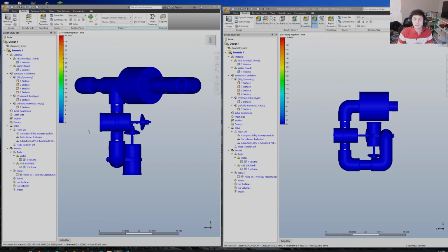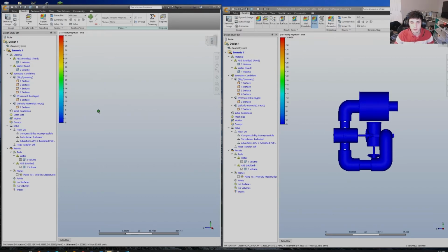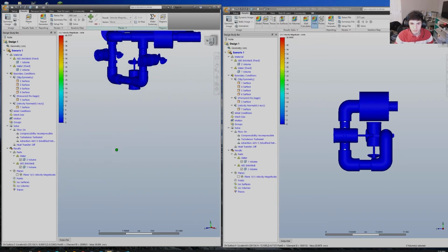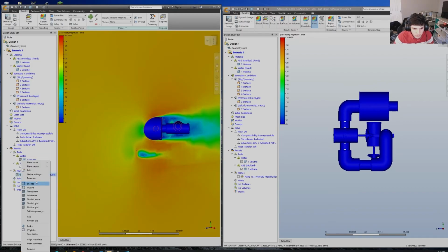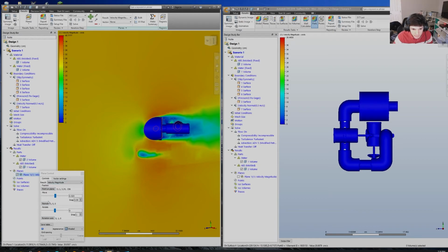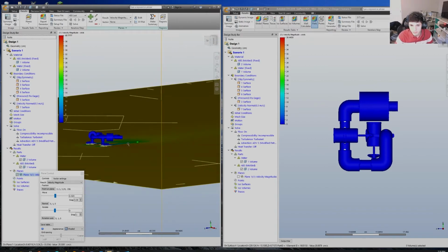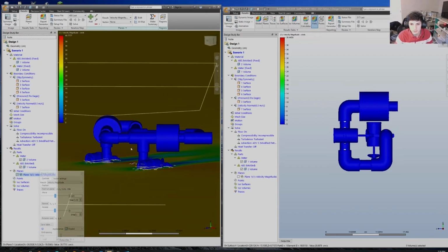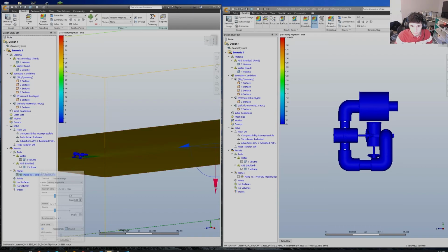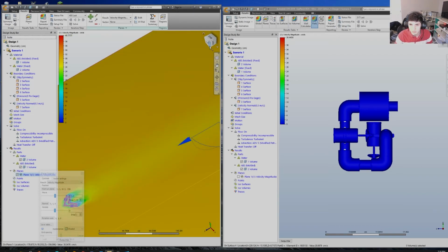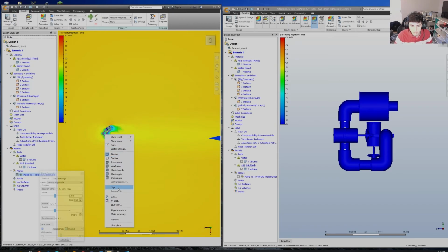And so here is how CFD might look for other types of ROVs. As you can see, this is more of a V-shaped ROV. Zoom in. And let's see how that looks with a plane attached to it. So let's enable this plane, edit. Let's make it horizontal. And let's say you want to see how much drag is caused by this V shape. So what you would do, move this upwards, go to the top view, hit clip.